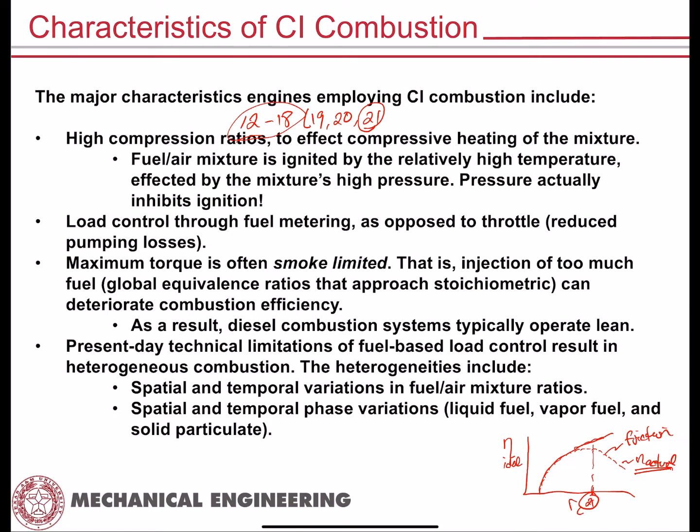Okay, so this is our first indication of what's going on with a compression ignition combustion engine, and that is that the fuel-air mixture is in fact being ignited by the relatively high temperature that is created by the high pressure of the high compression ratio, right? And of course, we know that pressure actually inhibits ignition, but high temperature promotes ignition, okay? And so we're using the fact that it's a high temperature environment to support that ignition process.